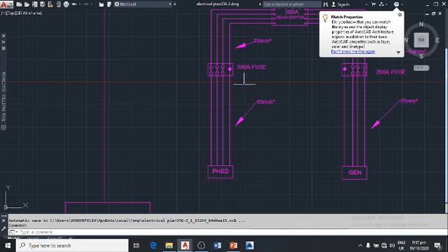This is because for a 500 ampere current coming into a building, the diversity factor might come in, because not all equipment in the building will be on immediately the light is coming. It's probable that 50% of the appliances are off, 50%, 60% or more appliances are off. Hence, this 500 amperes is the amount of current in our appliances. The 300 ampere fuse is going to cover for half of the amount of electric current that is coming.